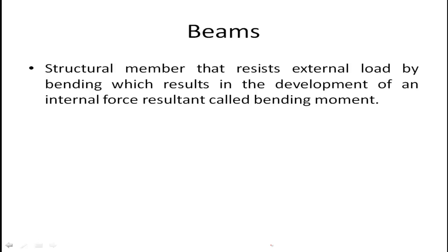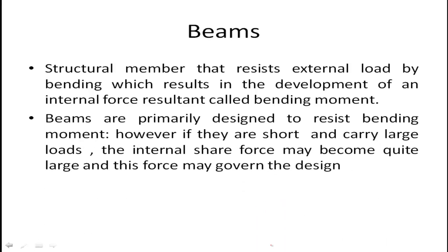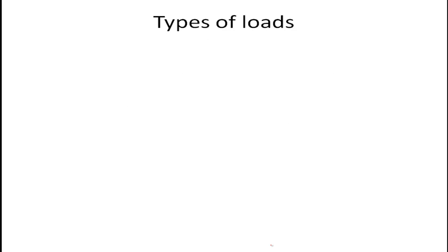The structural member that resists external load by bending, which results in the development of an internal force resultant, that's called bending moment. Beams are primarily designed to resist bending moment. However, if they are short and carry large loads, the internal shear force may become quite large, and this force may govern the design. Now, what kind of loads do we have to deal with in this course?